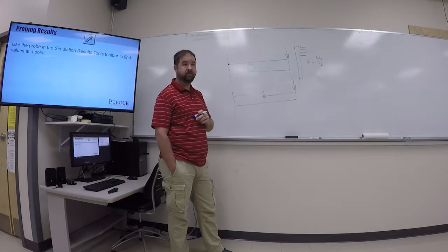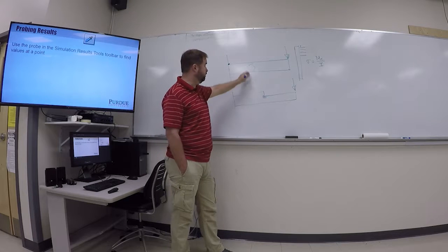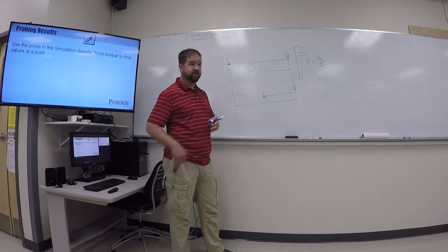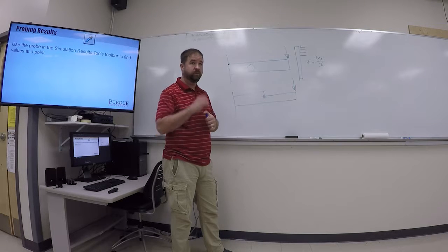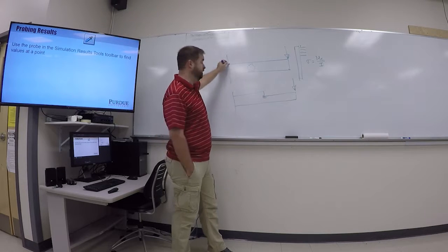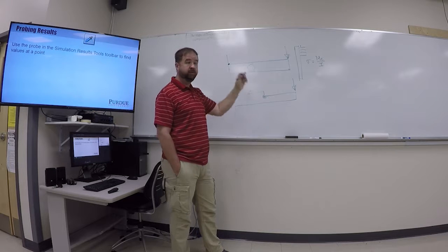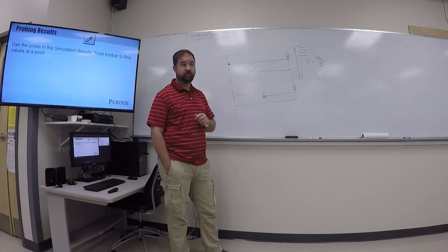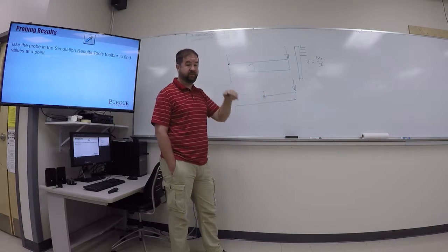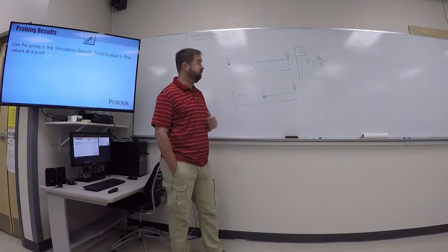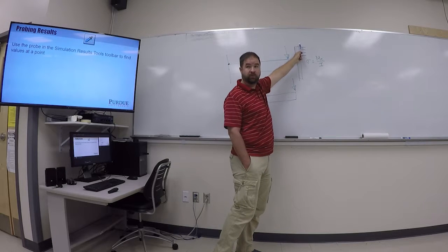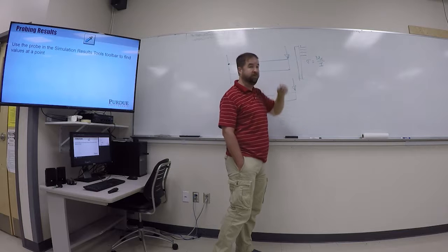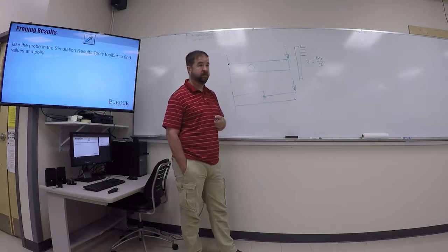So that happens a lot. You'll have a stress concentrator in there somewhere. Your hand calculation might not include that stress concentrator. So probe some known place where you know where the stress is, and then compare those values. Okay, that's a pretty useful tool. And I think that'll become more obvious as we go through these problems, that you can't just use the max value that SolidWorks puts on the graph, because that max value might not be something you're very interested in.